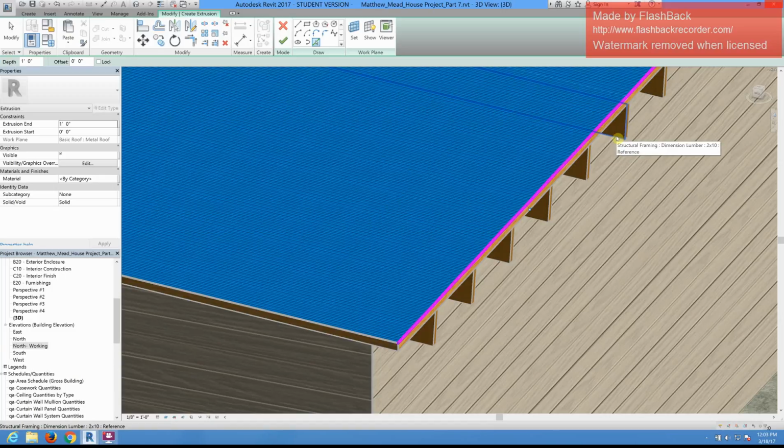And this is kind of a fine little detail that you may not be able to see on the screen. So what that profile is going to look like is like this. I just drew my bottom line, and I'm just going to draw the standing seam metal roof profile. Okay? So just for those of you who aren't familiar with some of these construction items, basically each of these metal pans is 1 foot. Okay? And they come in 18 inches, they come in 2 feet, you can kind of get them whatever you want. Okay? But we're going to draw that profile that we want to use.